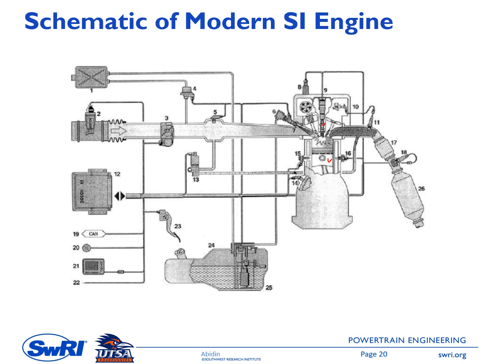This is the entrance of the air, so fresh air, which can be plus exhaust gas recirculation. Then I think this one is the sensor for the airflow, and then we have a temperature sensor, and then this is the fuel injector. I think it is injected before the intake valve, so it is PFI, port fuel injection.